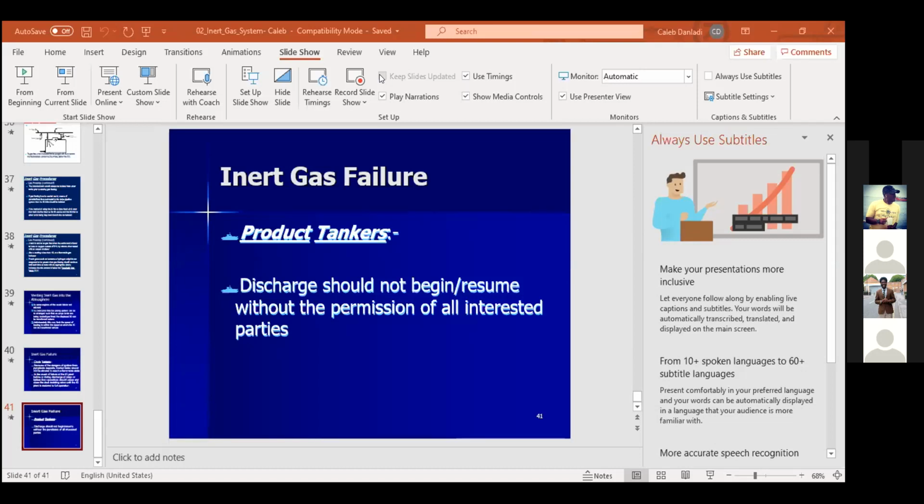Thank you very much for the wonderful contribution. One point I want to stress about your first contribution, if the ship is loaded and does not have space for ullage, you have to make reference to SOLAS, and the ship should never be loaded to more than 98% cargo.